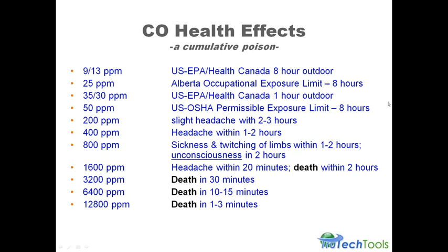The 327, 330, whatever combustion analyzer you're using, it actually watches stack temperature to determine whether it's in the condensing range or not. And with the 330, we can set up the analyzer to tell it that it's a condensing appliance or non-condensing appliance. But typically, it's stack temperature that determines that.